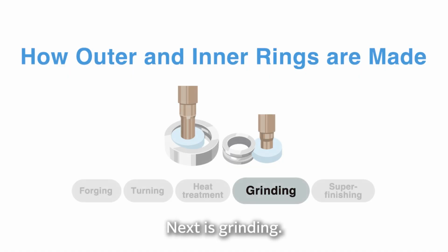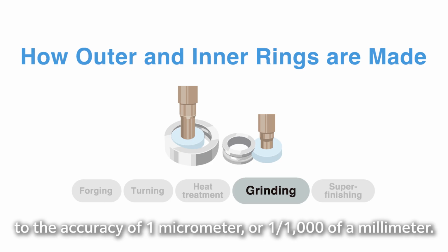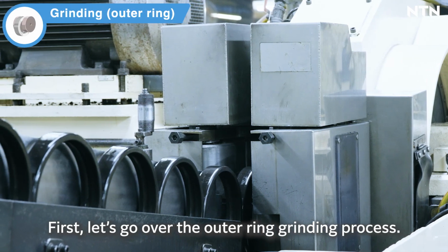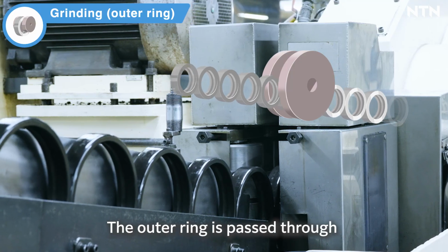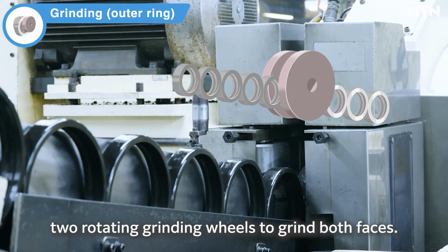Next is grinding. In grinding, dimensions are ground to the accuracy of 1 micrometer or 1/1000th of a millimeter. First, let's go over the outer ring grinding process. The first step is face grinding. The outer ring is passed through 2 rotating grinding wheels to grind both faces.